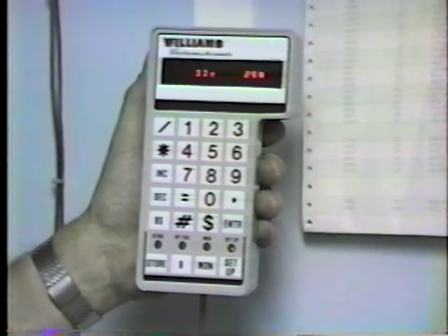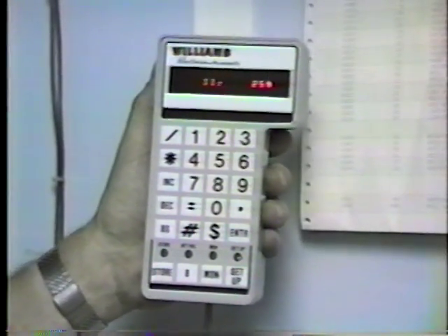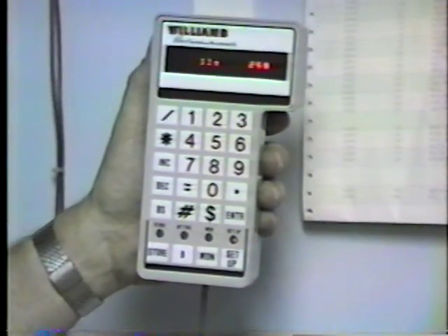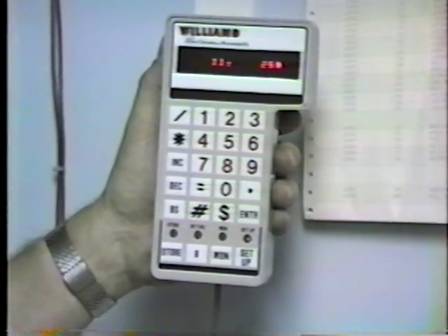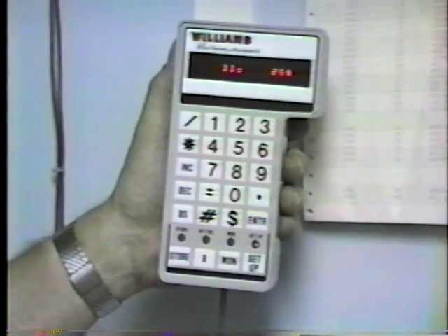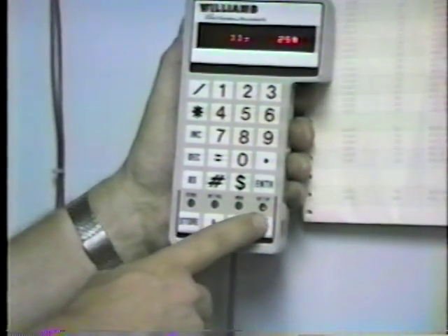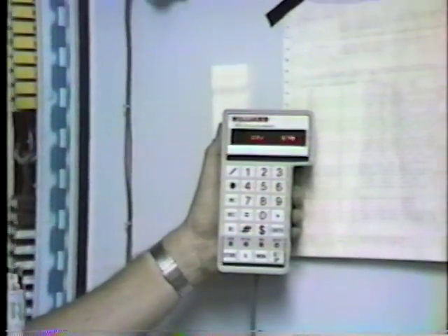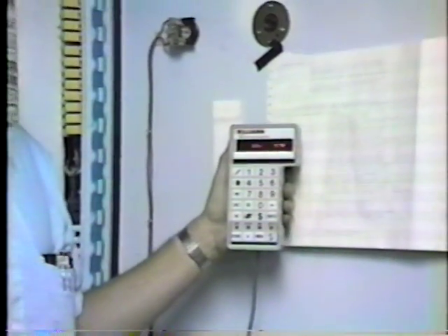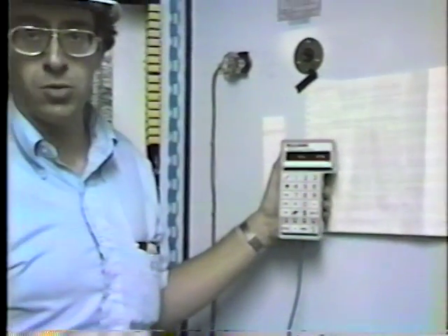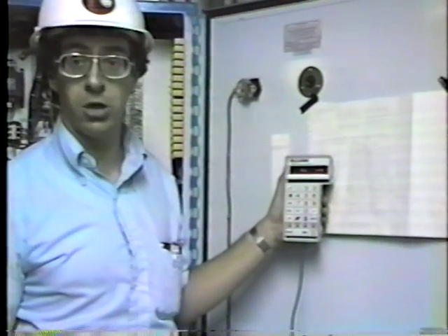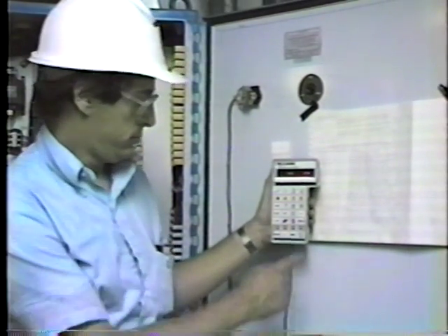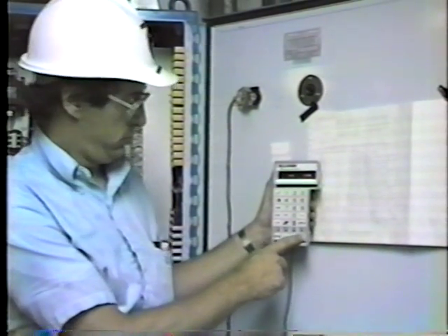What that means is as the mill speed goes up, the spinner speed goes down, maintaining constant 91, 92% minus material. Okay, next one. Number 12 is the ideal delta pressure at maximum mill speed. It's set to 67%, which is just a fraction over 2/3 of scale, or 10 inches. 10 inches. Okay, that has been set and should not change.